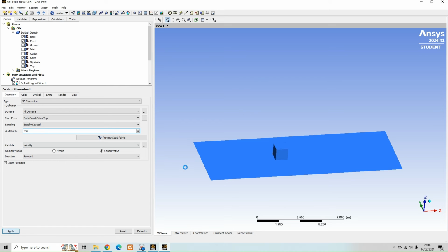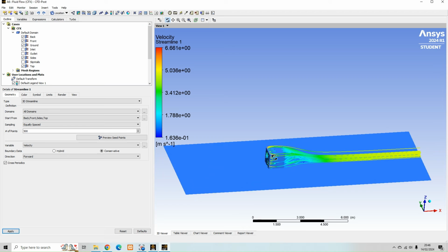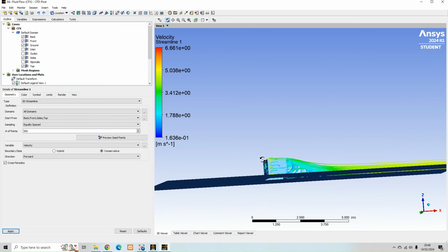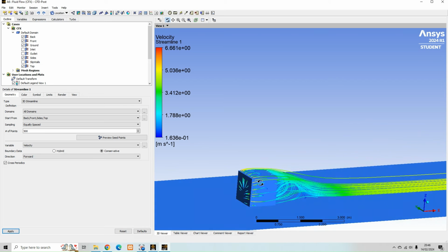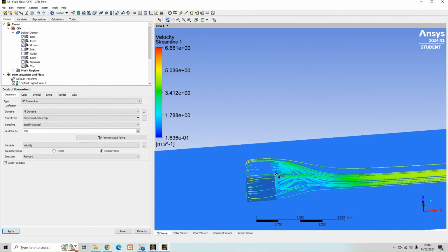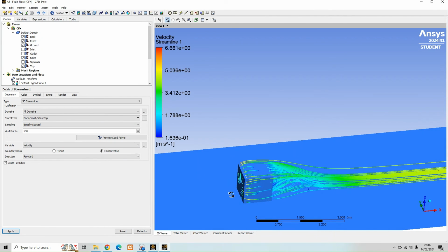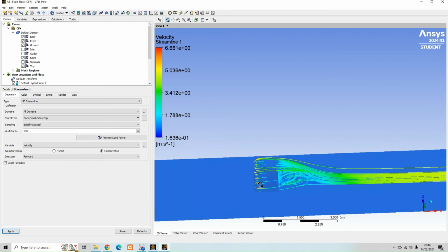So you normally need to do a little bit of playing with streamlines. You see there, some of them have just died, and it's just a function of A, the kind of flow physics there, but also B, the really high cell size. But you can see that kind of recirculation region. If you seeded them upstream, hopefully you'd see kind of horseshoe vortex formation around the front there, but that's good enough for us now.